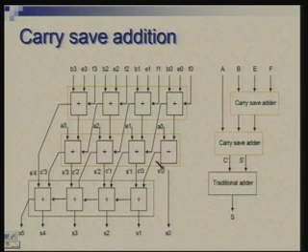So, in the last stage we have again sums coming out and the carries. These carries are being added at the sums position, and because we have to have a carry propagation here also. So, you would notice that the number of these adder cells is exactly the same, no more no less, right, but they have been rearranged in such a manner that delays are smaller.